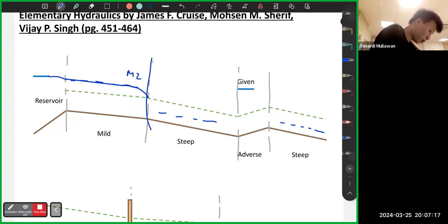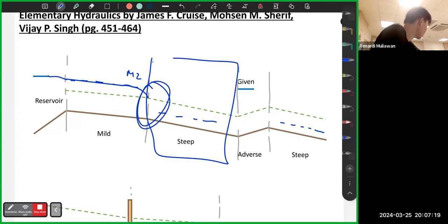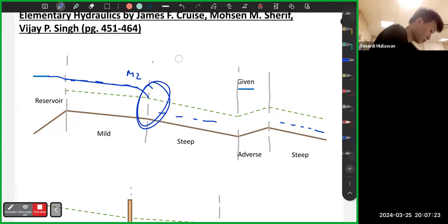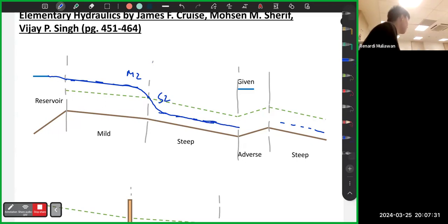Steep slope, if you draw a box, is again upstream control, and the curve is also upstream. There is something, so that's an S2. Then like this. Again, this one doesn't care because it's upstream control, but then you must go up. In that case you need a hydraulic jump. That's what I mean: if there's a mismatch, you need a hydraulic jump. I hope you all understand.